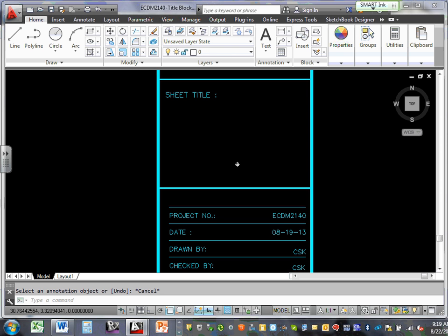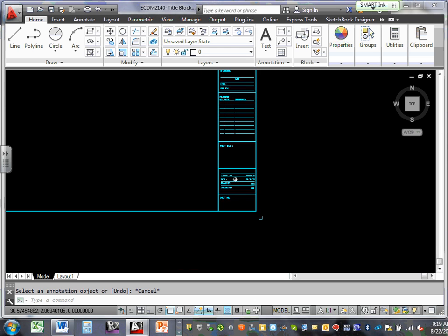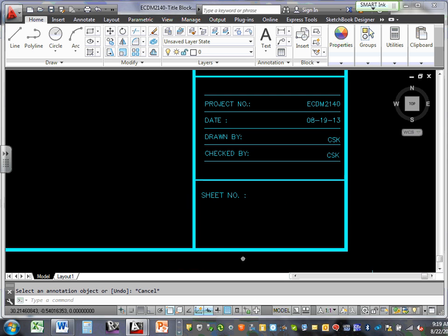Every sheet is going to have its own title. We don't do them here. Every sheet is going to have its own number, like E1, E2, E3. So sheet number is unique, so we don't do it here. Did you guys hear me? We edit the things that are common to all of them in the title block. Anything that's not common, leave it alone. It will be inserted in that sheet itself. Can I have thumbs up, Chad? We understand the difference? Okay. So all the stuff that you edited will show on every single sheet.